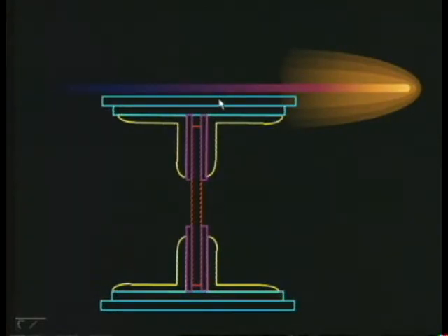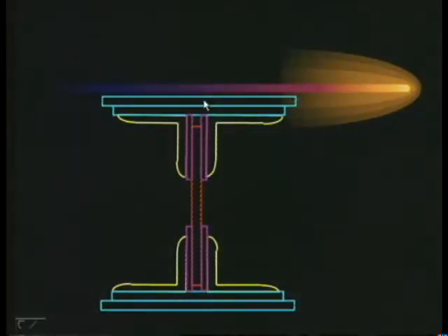When you have a long span, the bending moment will be more at the center of the section. So you can have the plate there. As we look at the bending moment diagram towards the supports, the bending moment decreases. So the top plate may be cut down to some extent. You can have the piece wherever it is required, and you can cut it down or curtail it wherever it is not required. That is called curtailment.